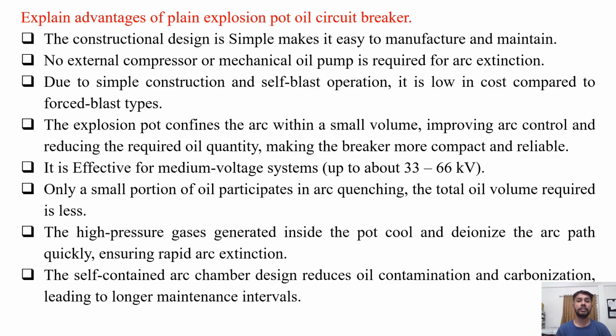Advantages of plain explosion pot oil circuit breaker. So there are several advantages of this type of breaker. The constructional design is simple, which makes it easy to manufacture and maintain. No external compressor or mechanical oil pump is required for the arc extinction. Due to the simple construction and self-blast operation, it is low in cost compared to forced blast types. The explosion pot confines the arc within a small volume, improving the arc control and reducing the required oil quantity, making the breaker more compact and reliable.